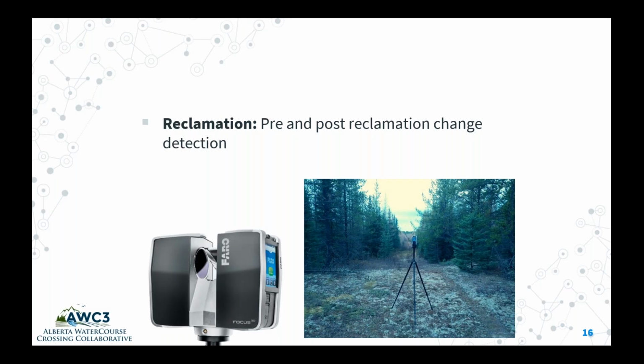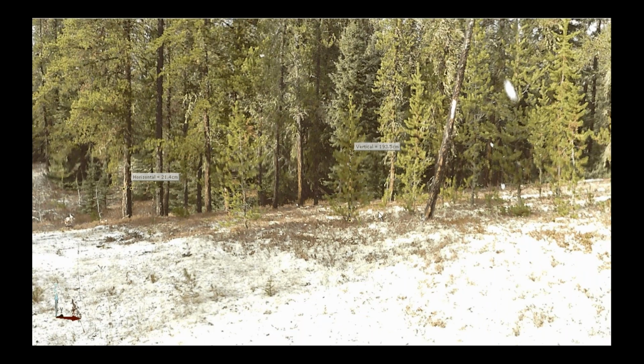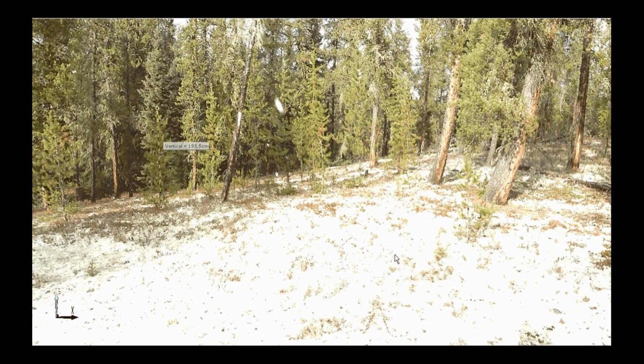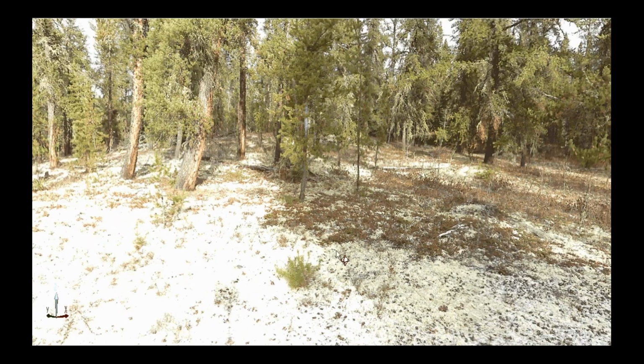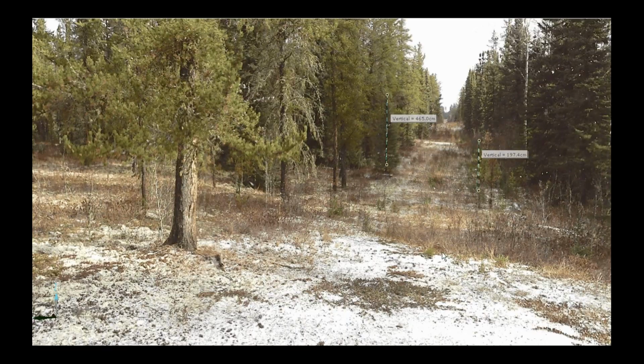Now, other applications that I have been involved with is in restoration of linear features like seismic lines. One can do a pre and post reclamation change detection using terrestrial LiDAR. Now you can see a Faro X330 scanner on the seismic line in this particular picture. Here is just the RGB from the 3D data sets, and you can pretty much measure or count trees and do other measurements within this 3D image.